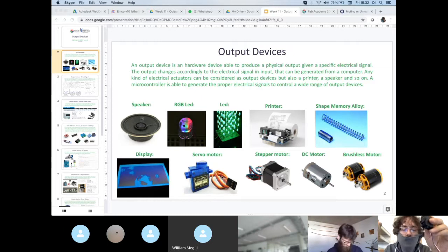The difference is that the servo motor will not work in steps. So you can finally move the shaft to any angle you want. It can be 55.63 degrees, for example. In that case, the comparison with the stepper motor is that you can just approximate that positioning with the number of steps, let's say.